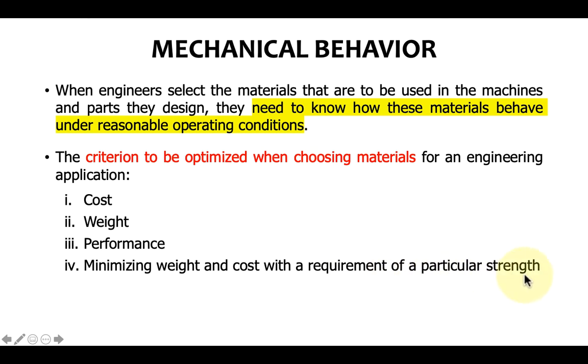The particular strength can be regarded as the constraints, which can also be called design requirements, which typically involve such mechanical behaviors as elastic modulus, meaning the stiffness, elastic limit, yield strength, and toughness. These mechanical behaviors can be expressed as engineering variables. Those variables must, in turn, contain the appropriate numbers and correct units.